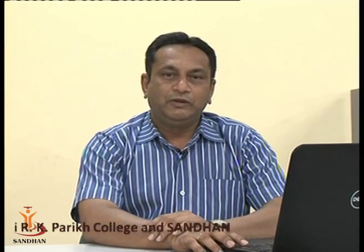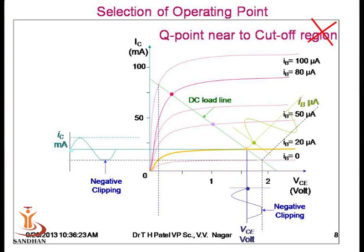Then where should it be? Okay, we take the second case. Suppose that the operating point is near the cutoff region. Under this case, we will find that clipping will happen at the negative peak. So this is also not a suitable operating point.